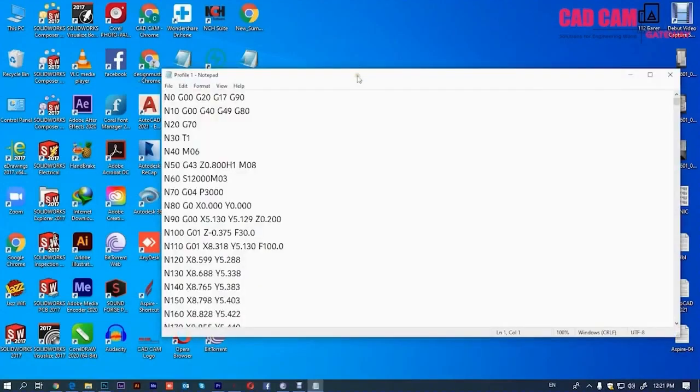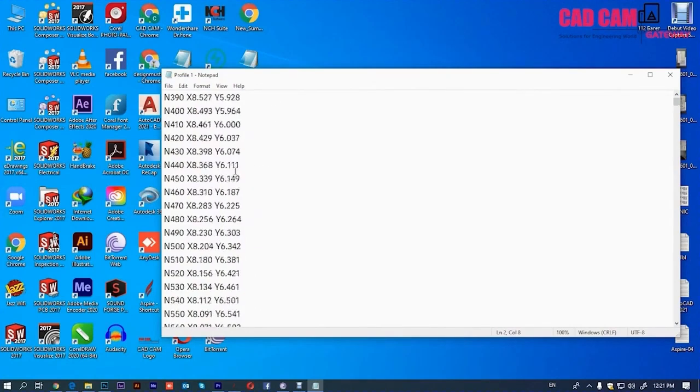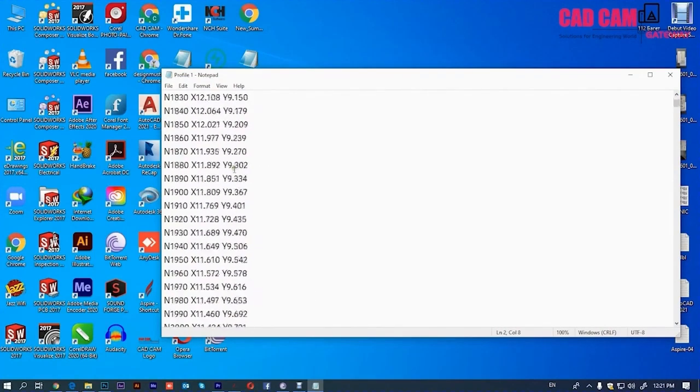So viewers, if we want to work on its programming file, like I double clicked on it, it uses both G code and M code. Look here, M code. M codes are basically miscellaneous codes. G codes are geometry codes. So the geometry is written through G code and the miscellaneous machine operation is created through M code. So it automatically wrote a complete summary that will help in programming.